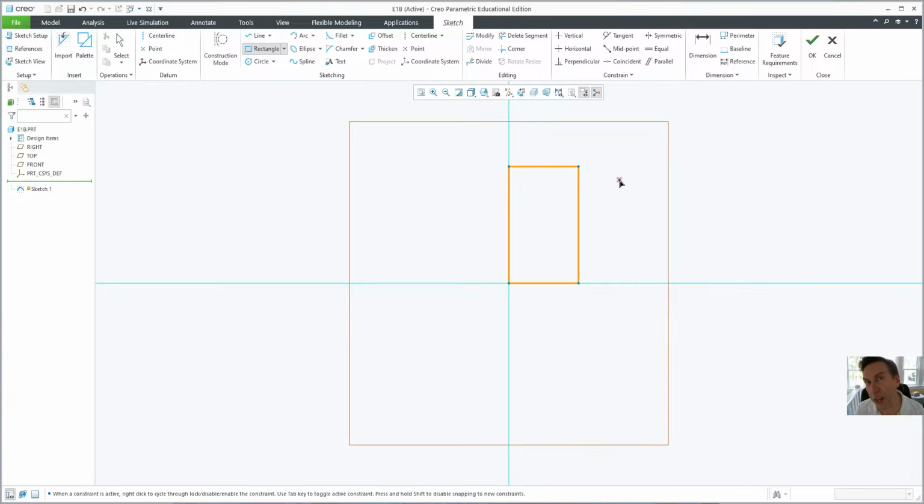The right mouse button and the middle wheel, I'll usually make sure I tell you, like, right mouse button, right mouse button. I'll try and say it twice so it triggers, oh, it's the mouse button we don't use very often, because you only use that maybe 10% of the time, and that brings up context-sensitive menu items. The middle wheel does some really neat things inside Creo, very different from most CAD systems. Very different, so pay attention and you'll learn some neat things.